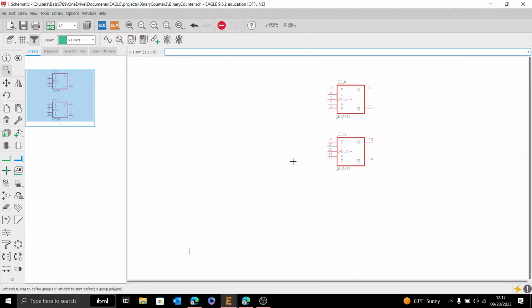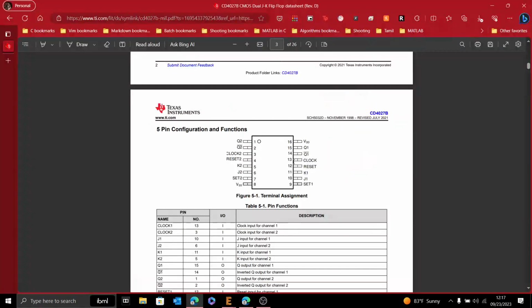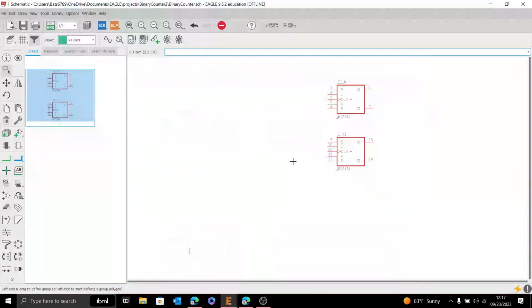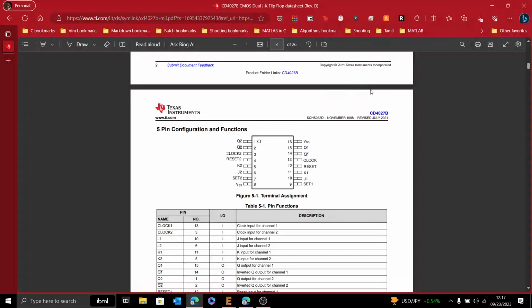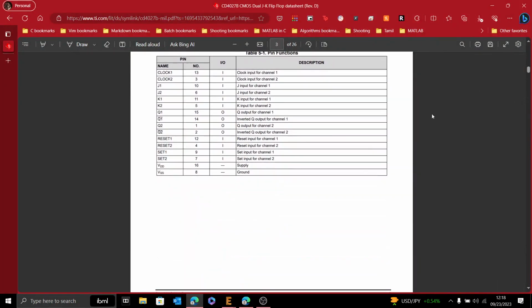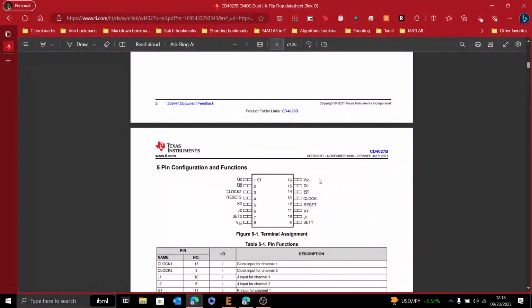If you look closely, one thing you'll notice is that Q2 goes to pin 1, whereas here it's Q1. Thankfully, I checked these close enough. They do map pretty much the same. It's just they flipped Q1 and Q2. So for all intents and purposes, these chips will function identically if we wire it up to this chip we're going to order. Now this is the surface mount. I think the DIP solution is further down.